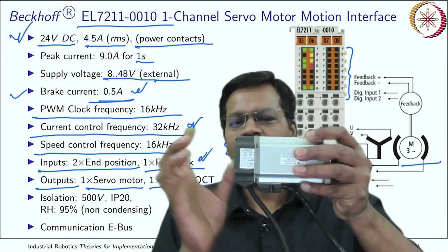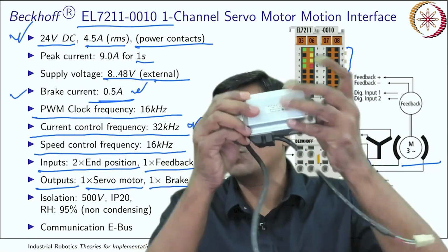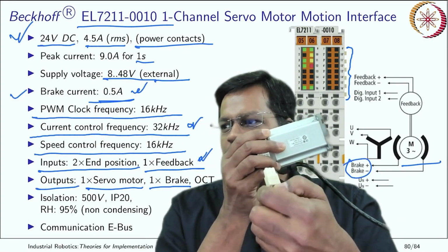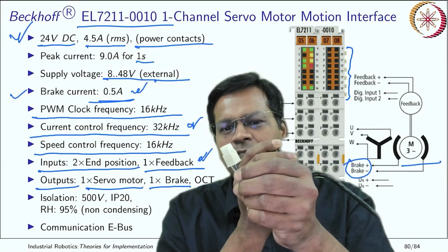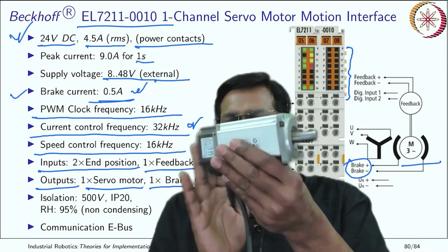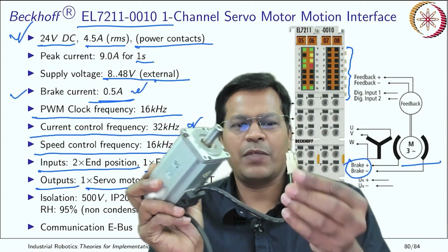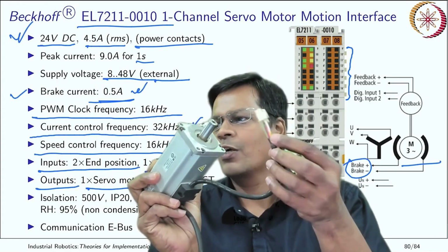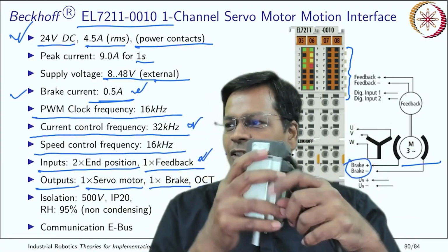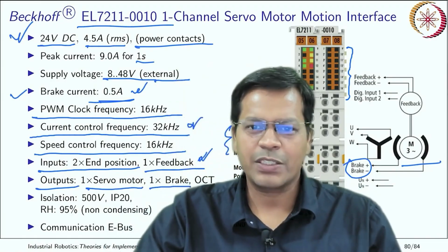So what is at the end? At the end, this section is nothing but an encoder. So you have 2 separate wires. This one is for the encoder wire. I can see plus VCC, ground, and 3 signals. So it may be a kind of resolver which gives you an output in 3 different wires. And then this is 3-phase and 1 ground, 4 wires. This goes to the motor part of it. So yes, this is how it looks like. This is a Panasonic one. There are many other makes which are making this kind of actuator.